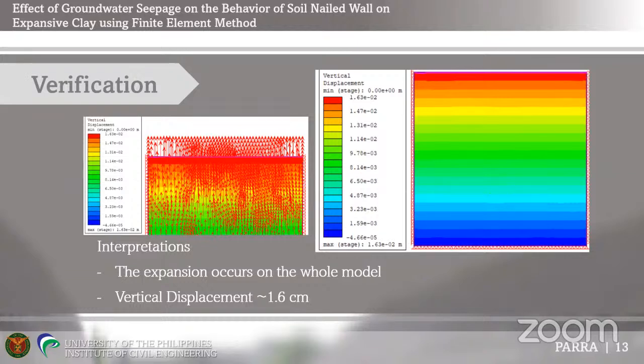And then as the water content changes, then the undrained shear strength should go up, because the void ratio will go up. So maybe that is what you need to look into, that's my comment. Okay sir, I'll look into that.